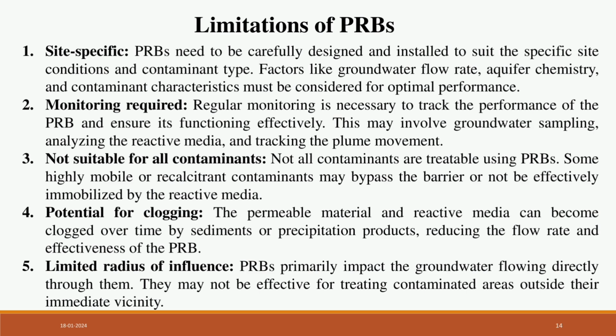Fifth one is limited radius of influence. PRBs primarily impact the groundwater flowing directly through them. They may not be effective for treating contaminated areas outside their immediate vicinity. Moving to the next slide, case studies.